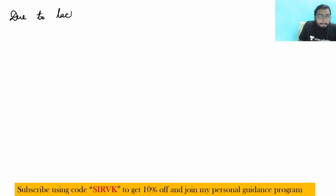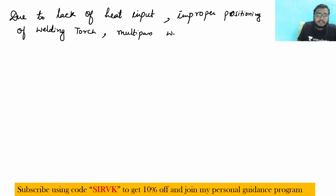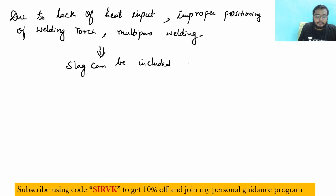Due to lack of heat input, improper positioning of the welding torch, or if you are conducting multi-pass welding, slag can be included in the weld joint.